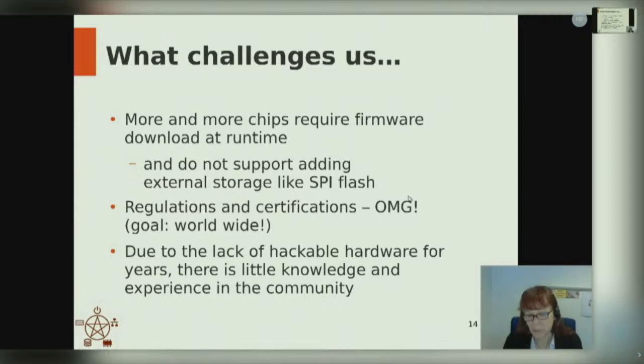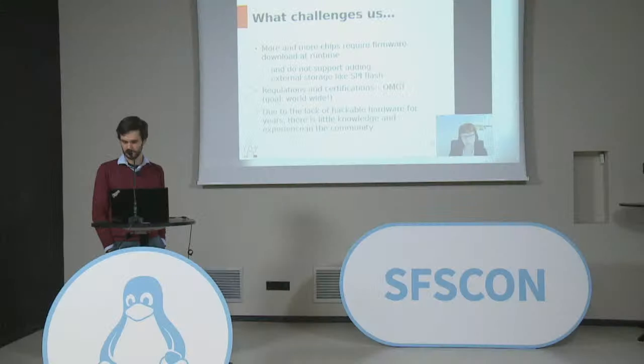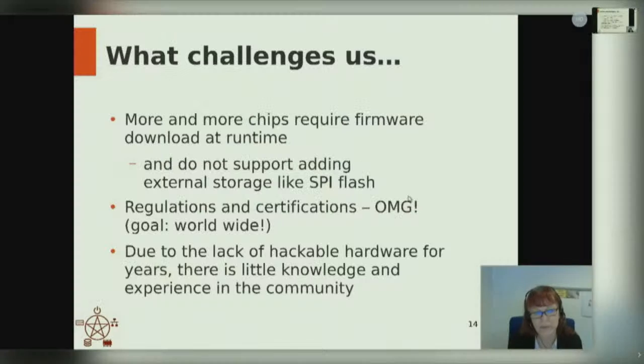Then another big challenge is, I already mentioned this briefly, more and more chips these days require firmware downloaded at runtime through the host CPU and the host interface. In the earlier days, it was quite often possible to add an external storage to those chips, like an SPI flash, and have the chip download the firmware into itself, like a Wi-Fi card or a modem, something like that. But more and more complex chips require the host to download this firmware into the chips.